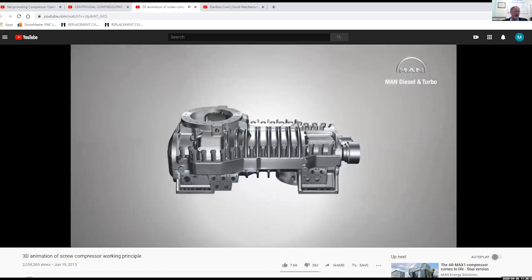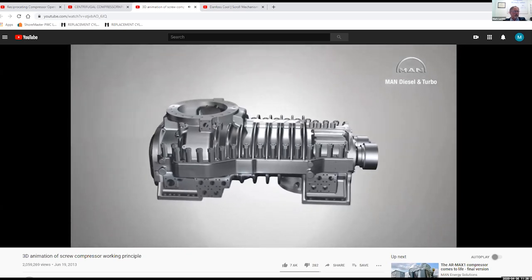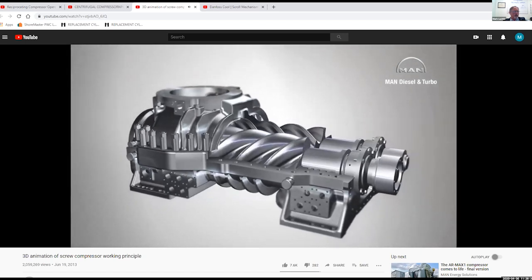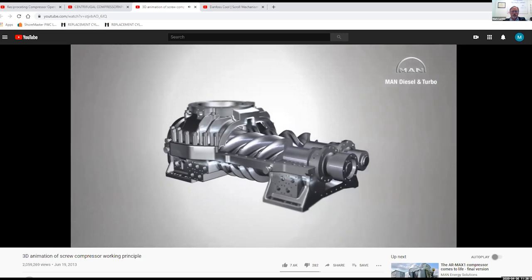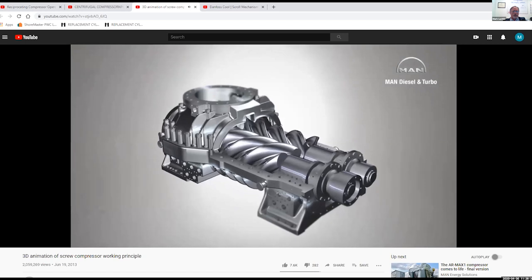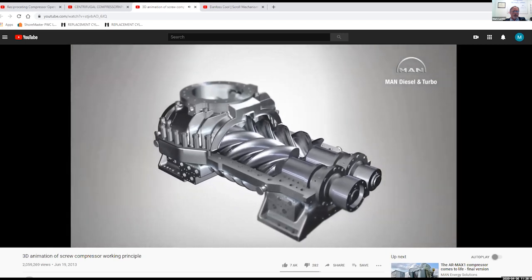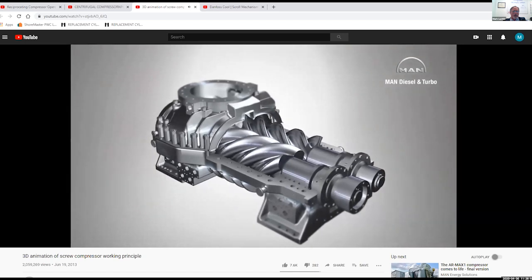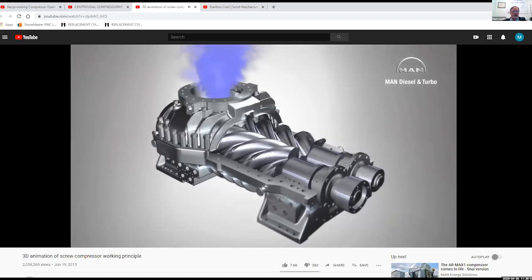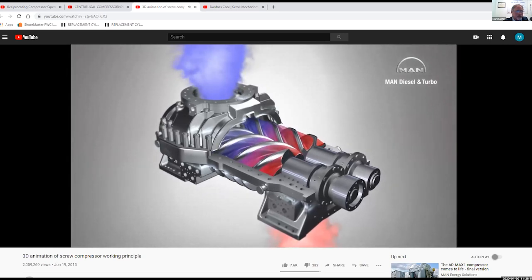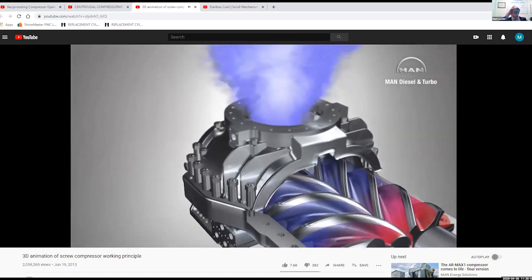All screw compressors operate according to the basic principle of a positive displacement machine, whose key element is a pair of spiral rotors. During operation, the rotors turn and the spiral teeth mesh together, forming chambers between the rotors and the casing wall. Rotation causes the chambers to move from the suction or intake side to the compression or discharge side. These chambers are connected to the suction nozzle via ports. As the chambers enlarge, they are filled with gas flowing in through the nozzle.